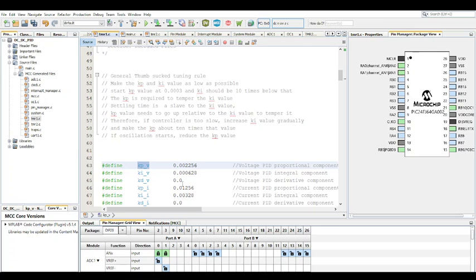So there's like a window there where you can increase the KP, where you can increase the KI to make it settle faster. You decrease the settling time, help it reach the set point much faster. Basically, you're increasing the KI, and then you have to increase the KP. Every time you increase the KI, you have to increase the KP by a certain degree.